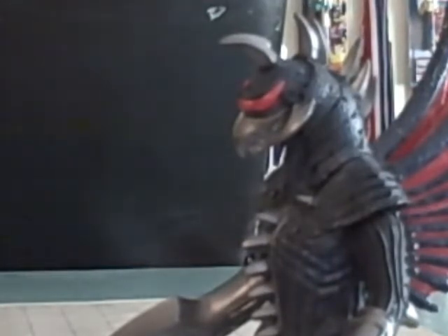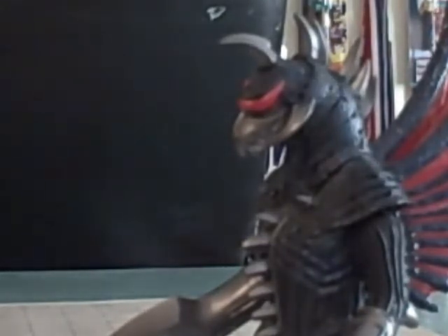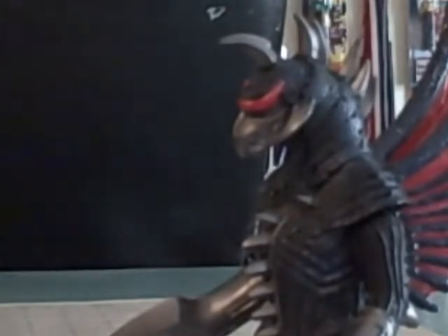Also, there are disadvantages. It requires positive confinement. Obviously, you have to give it some shape. And also, if you use something like oil, it's explosive or flammable, which can be extremely dangerous. So filtration is critical. It has to be free of debris. You don't want an explosion on our hands. Also, manpower can be intensive in cleanup. You're gonna need a lot of fellas to tote that stuff.